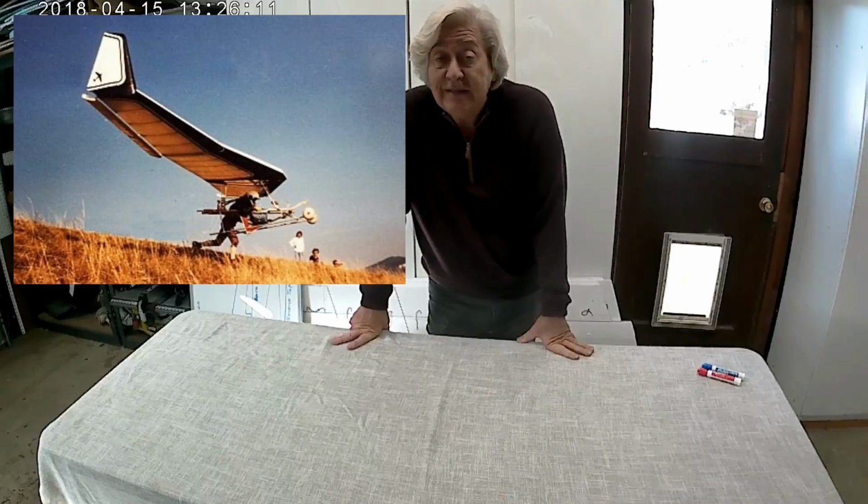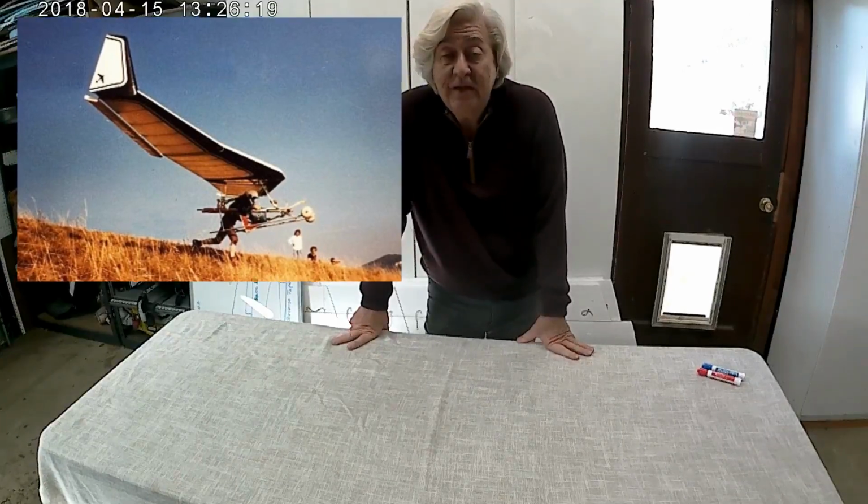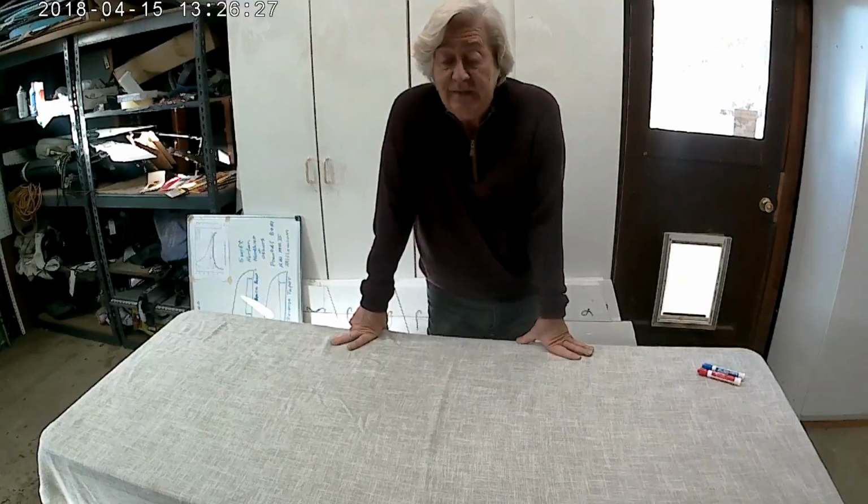And word has it that the Mitchell wing still had some nasty spin tendencies if you got the CG a little too far aft. In fact, somebody related to me once that they were stuck in a spin in a Mitchell wing for a while, and they were just glued up to the side of the pilot's cage, and they weren't sure they were going to get out of it, but they did. They were lucky. Got to get that CG forward, and don't fly it that slow again.